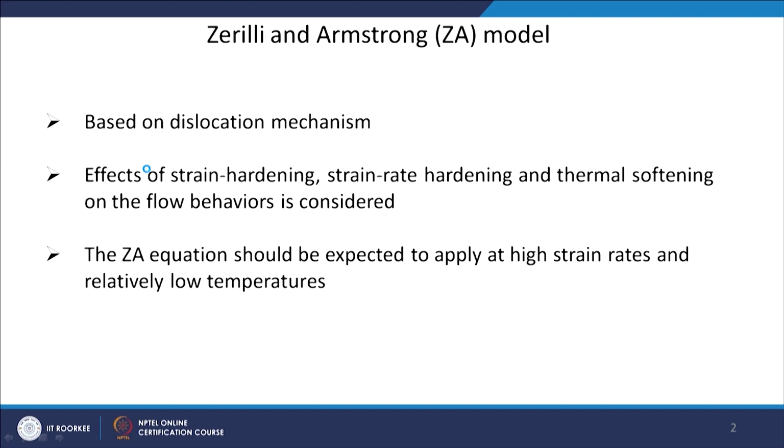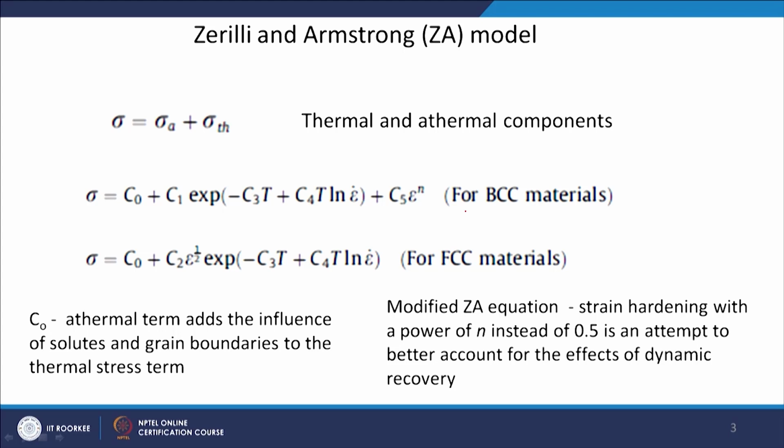You can consider this particular equation for high strain rate and relatively low temperature conditions, and apply this model to develop a constitutive equation. What it does is that the stress is calculated by considering two contributions to the stress.